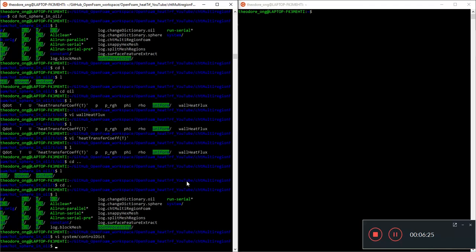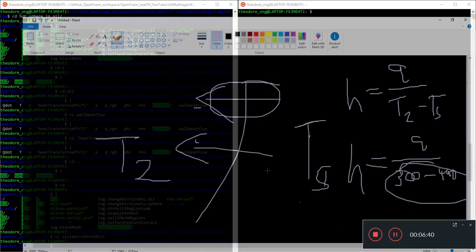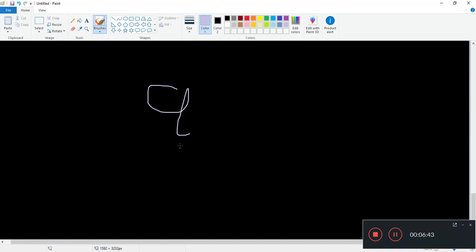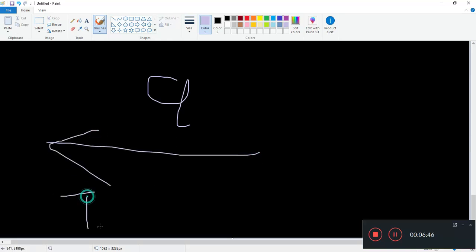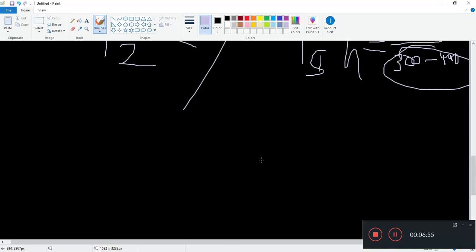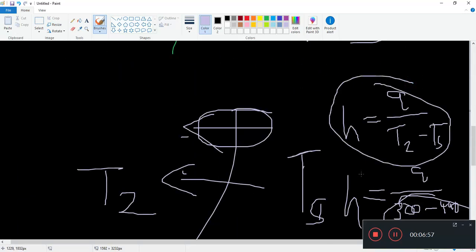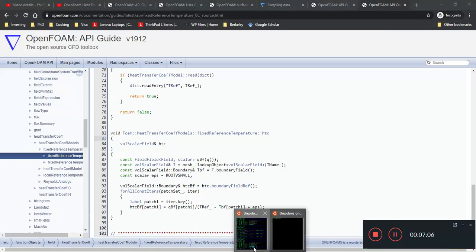Oh yeah, it should always be positive, because the heat transfer coefficient should be sign-indifferent, regardless of whether the heat flux is traveling to or from the fluid. Because if the heat flux is going this way, and the temperature difference is this way, that means here should be a lower temperature than here. The formula kind of takes care of it for us, because the temperature differential direction is already captured in the formula. So anyway, let's try this.